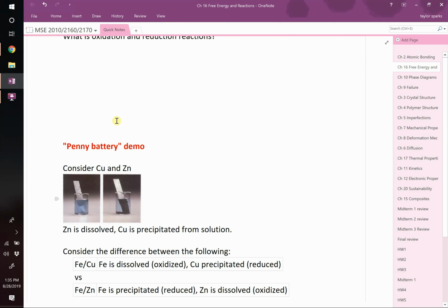And you've seen this before. This is not the same thing as your bathtub faucet. If you've ever seen the white stuff building up on your bathtub faucet, that is not the same type of corrosion. That's probably just precipitation, meaning all the dissolved solids in our water, the calcium deposits, are just coming out of solution when they find a nice surface and they're nucleating on it. That's different than electrochemical corrosion, okay? Because it doesn't involve the exchange of electrons. Electrochemistry has to be driven by the exchange of electrons, okay?